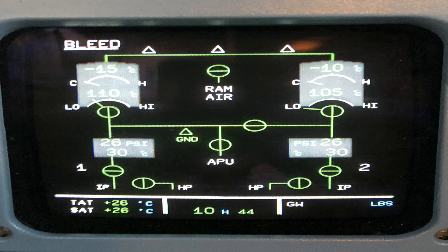All right. So you got the fault legend on the engine 1 and also the engine 2 and the APU bleed push button switches. And those are going to come on if there's that overheat condition. Okay, so that kind of gives you an idea of what the chain of events is, what happens when you have a fault, when you have an overheat: valves are going to start closing.